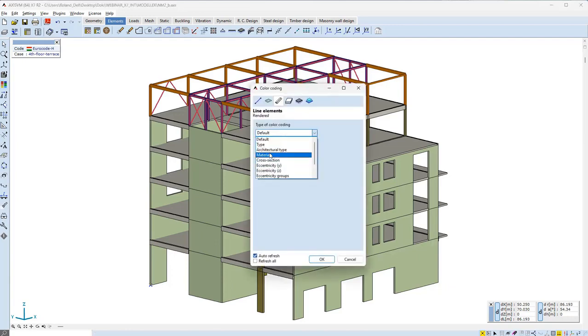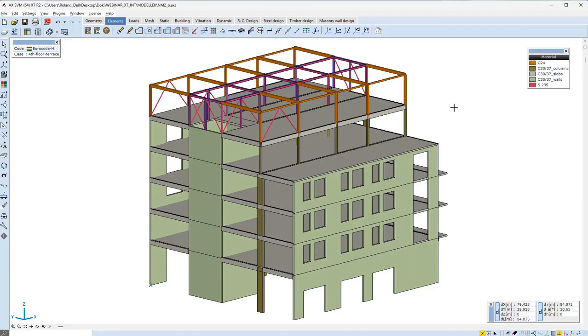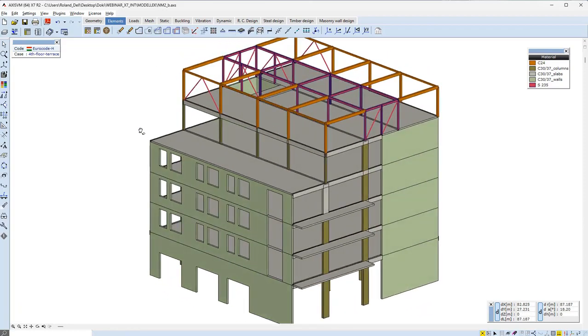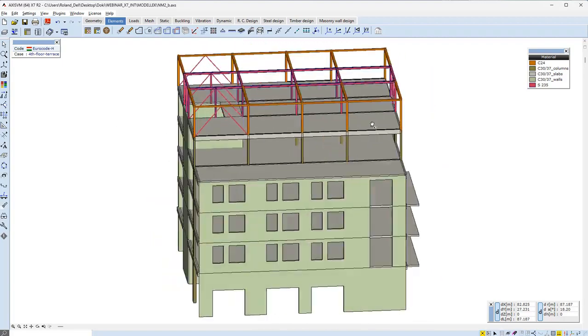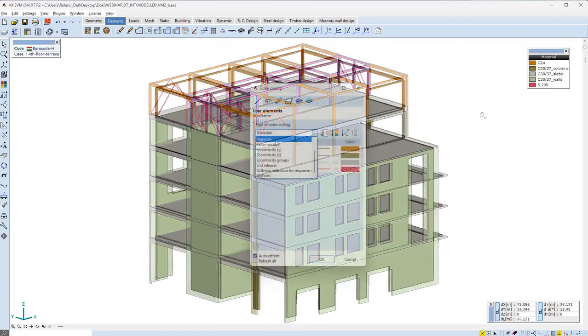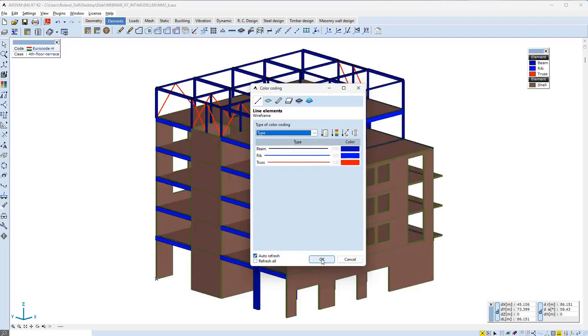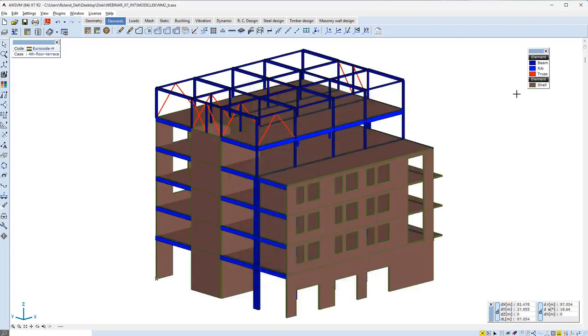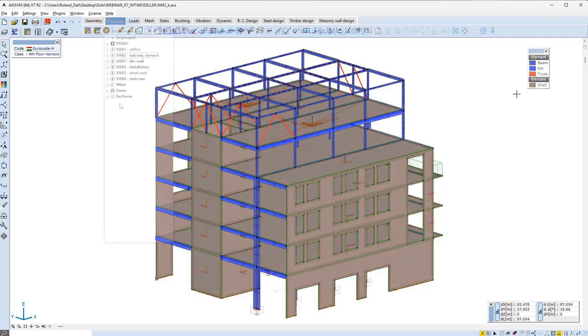The structure which is being used is a multi-story residential building. As the color coding shows, it is built up from concrete walls and floors, having a steel structure mixed with timber on the roof. Element type-wise, steel and timber members use the 6 degree of freedom beam element, bracings use the 1D truss element type, wall and floor domains are defined as shell elements, and members in the plane of the floor are defined as a rib type of element.